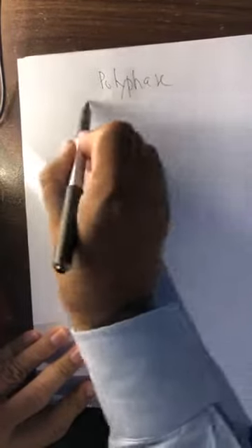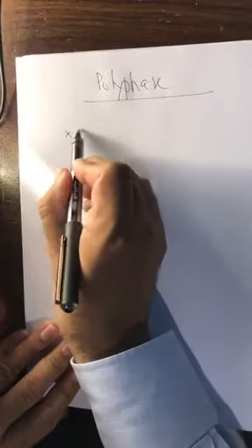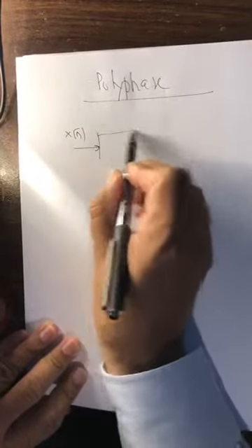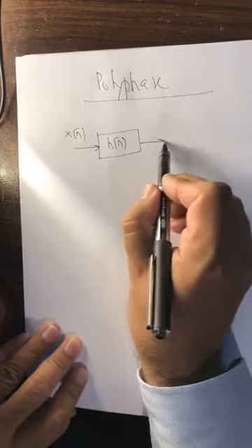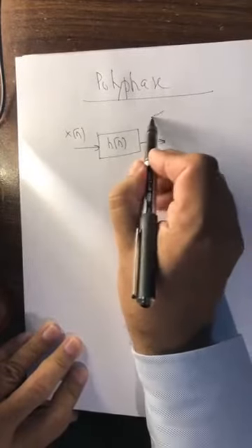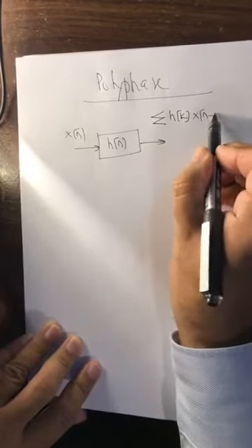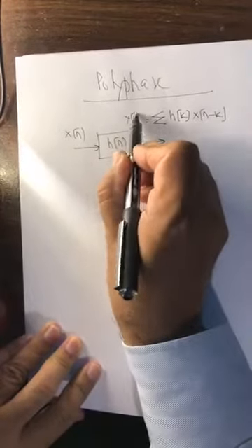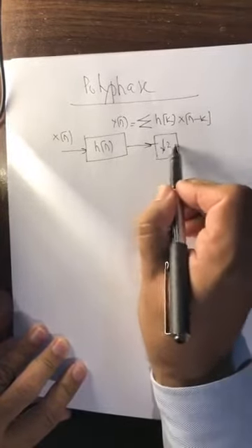Now really one important thing which leads us to polyphase filters is that remember that you have the signal x of n, you design a filter h of n, this is your decimation filter, so you do convolution. You perform convolution. Convolution, you know the summation, which is h of k x of n minus k, y of n. So you do multiplications, additions, and then you throw away half of the samples, right?